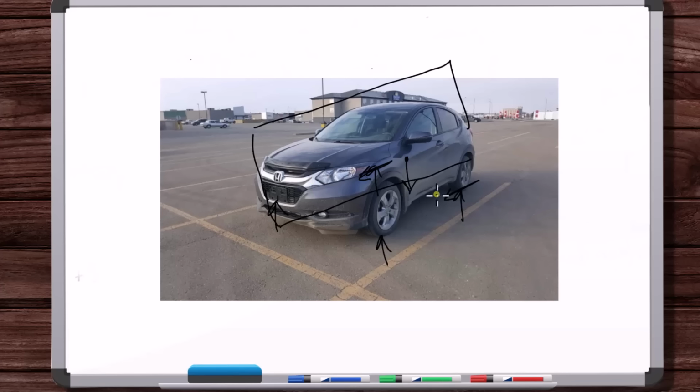And so another way to think about this is, all right, technically there's these areas of contact. There's a distributed load here on the tire, some sort of distributed load. There's a distributed load in the traction direction as well, all in that area of contact between the ground and the tire, right? Same here, same with all the tires. Well, okay, we learned how we can take any force or couple moment system, and reduce that down to an equivalent force and couple moment.